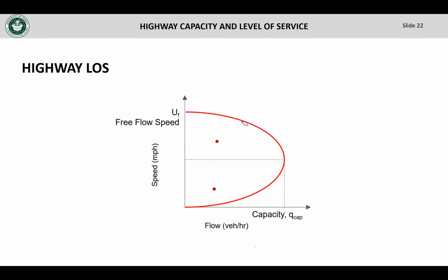And really, for the highway capacity analysis, we're going to look at a lot of different details, but it boils down to the following. If you remember the fundamental traffic flow relationship, Q equals K times U, and I just told you density is what is going to define our level of service. So basically we're going to need to find a speed for a given flow, and the ratio will be given as the density. And that density will define the level of service.